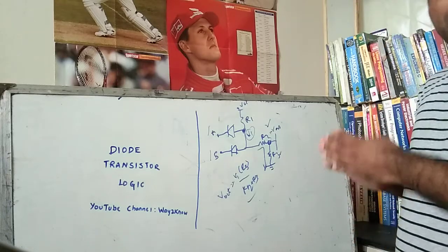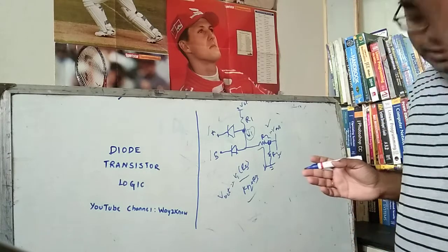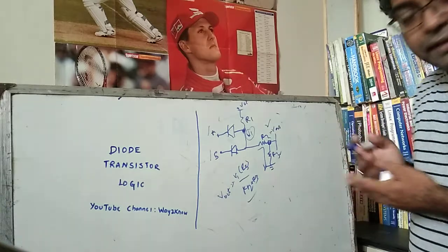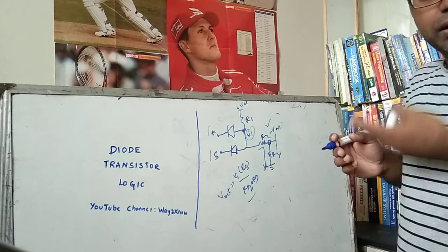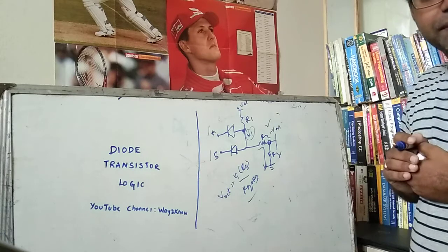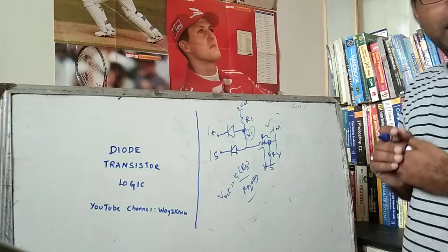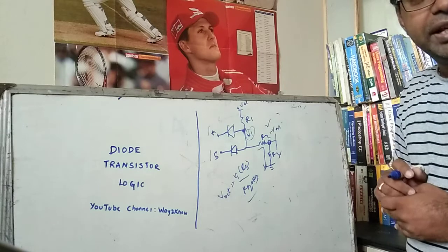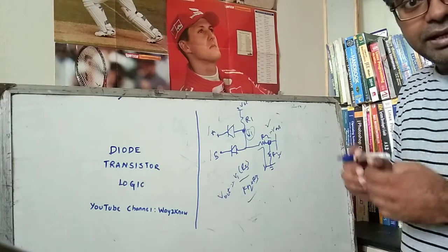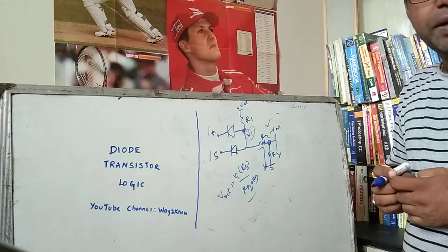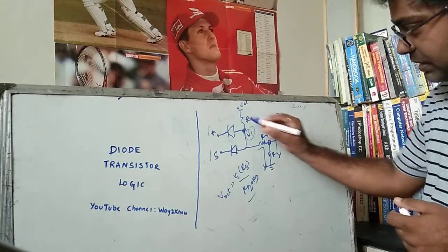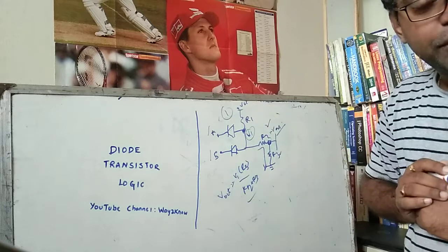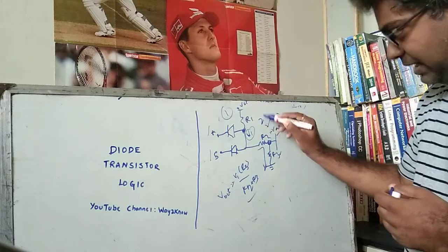This level shifting can be done by diodes as well, because if the resistors are considered to be consuming power, we can have diodes in place of resistors, or a Schottky diode here, where it improves the speed of the operation. And this is the first stage which we talked about in the diode section, and there is a second stage.